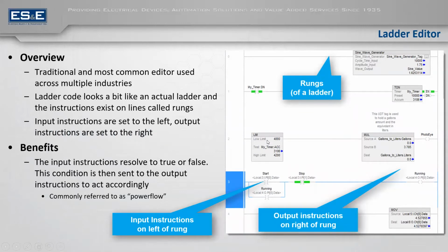So most PLCs come from this style. Ladder logic is the traditional, most commonly used, especially in the Rockwell world. Some other platforms are very hybrid between ladder logic and potentially a structured text or a higher function style like that. The benefits for ladder logic are that you get to see that power flow, or see what is actually executing.